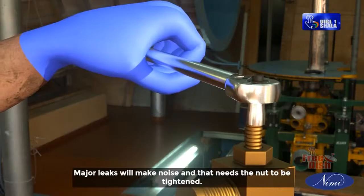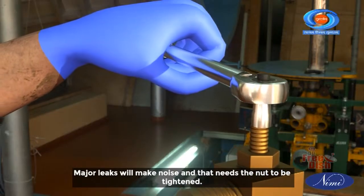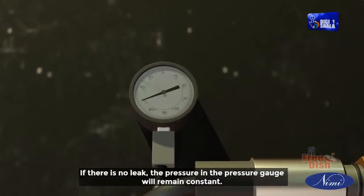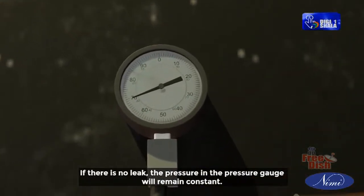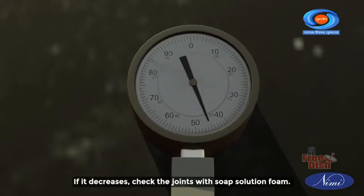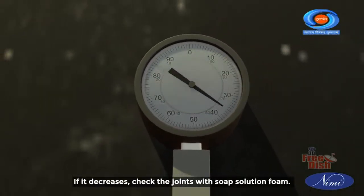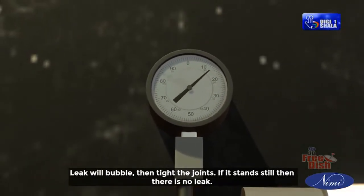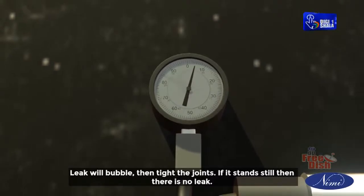Major leaks will make noise, and that needs the nut to be tightened. If there is no leak, the pressure in the pressure gauge will remain constant. If it decreases, check the joints with soap solution foam. A leak will bubble; then tighten the joints. If it stands still, then there is no leak.